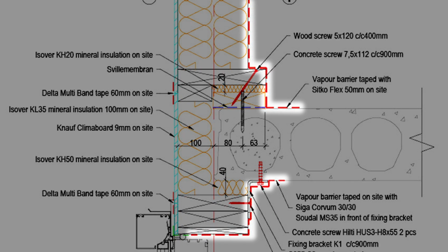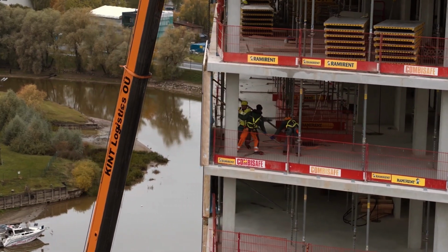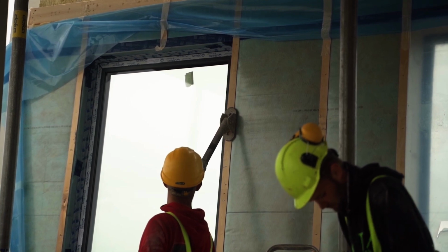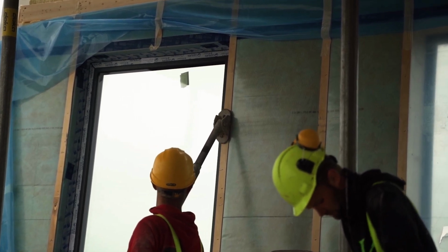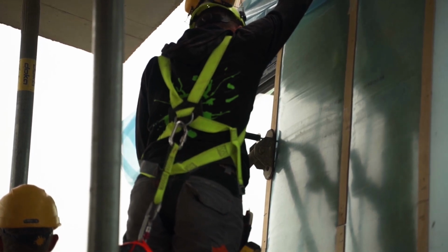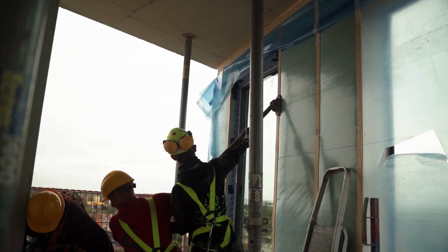Depending on the contract, site work may also include some internal work and additional work related to the external cladding. During the quality control of the work, it is monitored that the joints of the building's vapor barrier and wind barrier are properly sealed, and that there are no empty, uninsulated air pockets between the elements and the load-bearing structure.